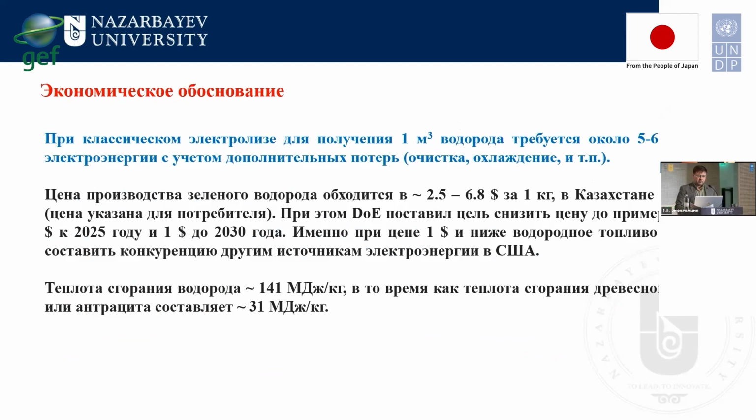And if we go to the economic justification of the whole catalysis process, in classic electrolysis, when you put two electrodes into water and then current is going through them, in order to get 1 cubic meter of hydrogen, you need around 5 to 6 kilowatt hours of electricity. But we need to take into account additional losses for the cleaning of the hydrogen, because there is some steam involved as well, and cooling is required.